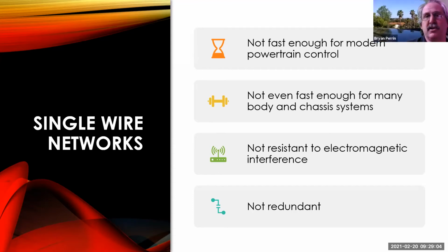Same thing. Self-driving. Some of the cameras are modules. Some of them are just feeding a video input to a module. It depends on the manufacturer. Now, if I'm talking radar, those are modules. So the radar is going to be on the network. It's going to be on its own network. But the cameras are not all modules. A lot of them are just dumb cameras hooked up to the main module. So it depends on the manufacturer with the ADAS system. And that's why it's important to look and see what you're working on, how they build it. Got it.